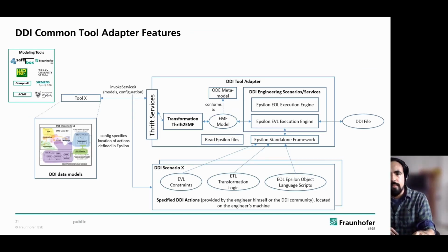And the tool chain that we developed during the DAYS project has enabled us to take a first step towards this by using this common DDI tool adapter. So the purpose of this adapter is that you can take each of your tools, for example, you can take SafetyBox and any of the other tools that are mentioned here. And you can use this tool adapter to convert between the common DDI format, either via file or by executing intermediate scripts, and be able to transfer your information across tools and eventually into a combined model, which you can then exchange and reuse.